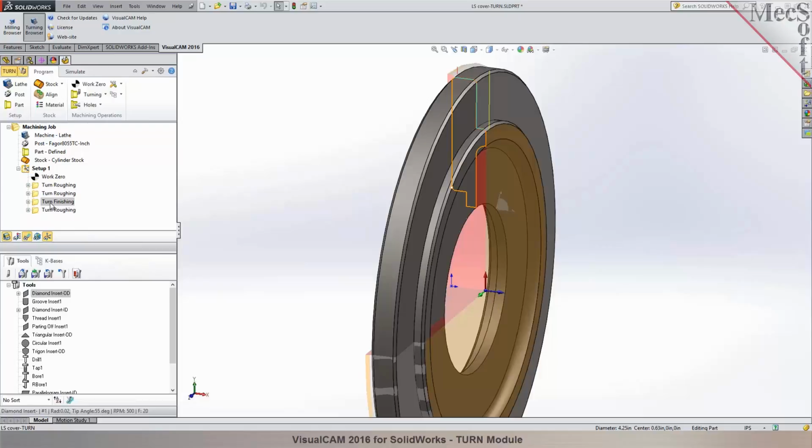But it looks like you will have to face one face of the part somewhere else. But we're going to have to do one face on one end, but then we can use the bore as the reference, and then we turn around the piece and we face the other one and we do the counter bore on the other side, right? Okay, makes sense. Yep, you're right.